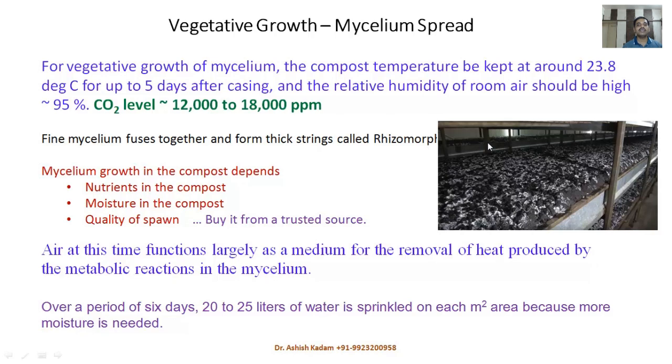So your PLC will continuously monitor your room conditions, and accordingly it will modulate the valves and the dampers in the air handling unit, and it will ensure the right environment for the vegetative growth of mycelium.